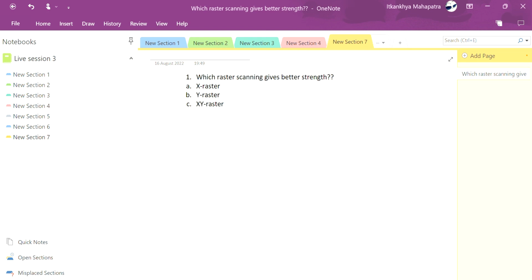How do we regenerate those missing triangles? The missing triangles in an STL file can be regenerated. There are various operations like transform, repair, shell, rotate, translate. From these, the repair option lets us generate the missing triangles. This is one more question.